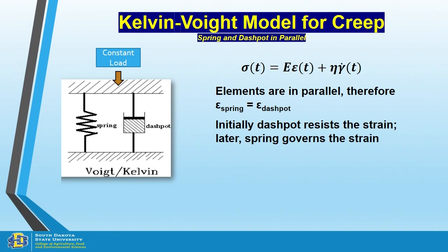You cannot do this experiment in your texture analyzer. Remember that, because you have your food sitting there, you just need to put some weight there, and then you need some type of instrument, a transducer or something, which can monitor the deformation.